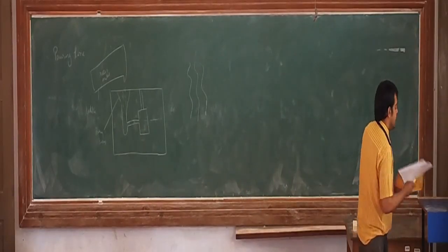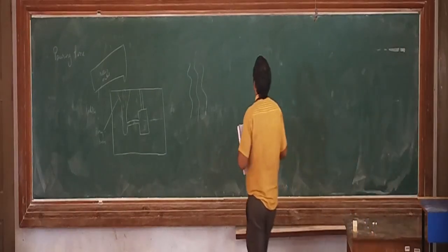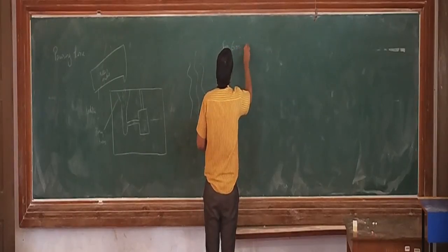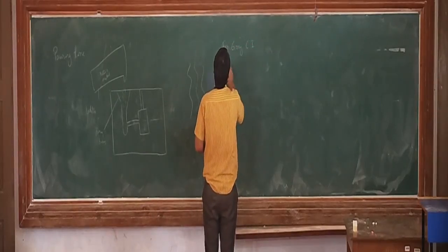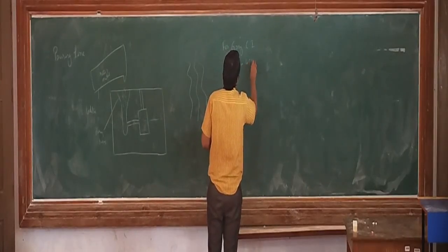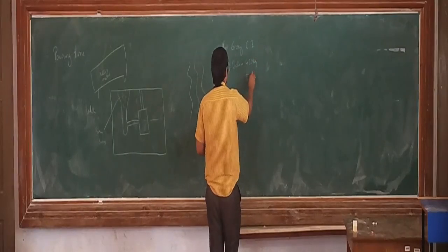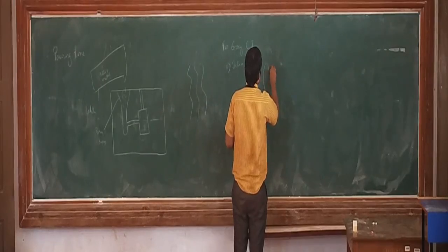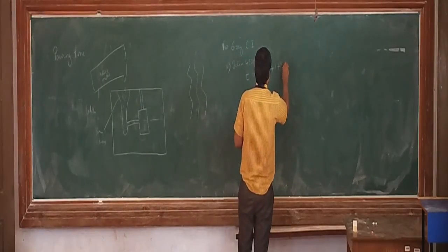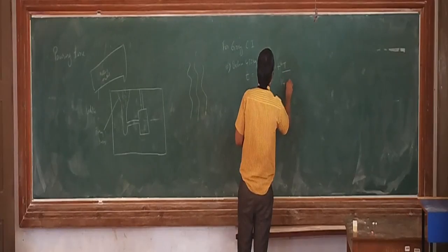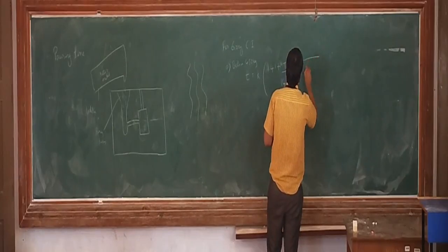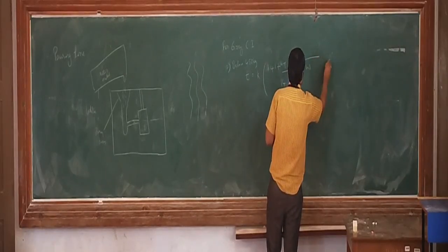So the pouring time T for grey cast iron below 450 kgs is T equal to K into the bracket 1.41 plus T divided by 14.59, whole multiplied by square root of W, in seconds.